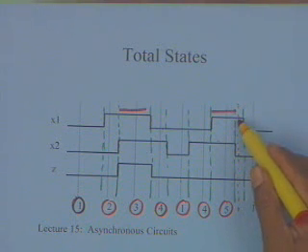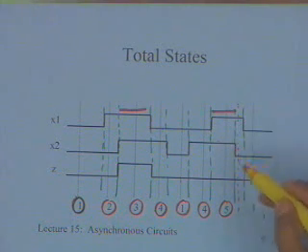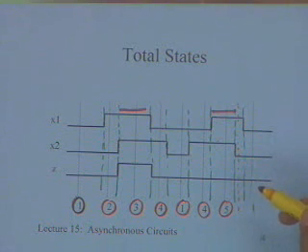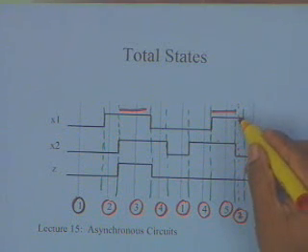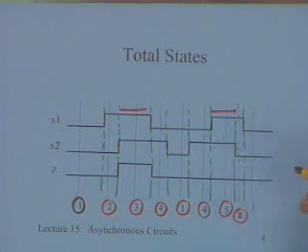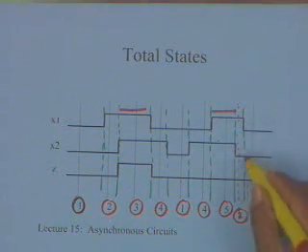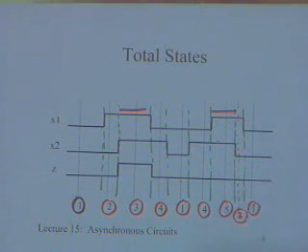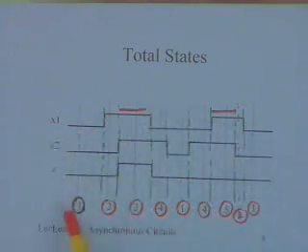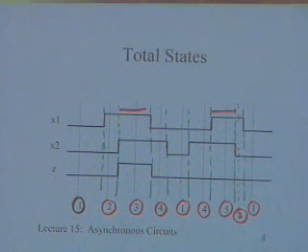So once I go to this 1 and 0, what will be the stable state here? I do not have to distinguish here, because anyway x1 is 1 earlier, then x2 is 0. So when I am 1 0, I can actually go to stable state 2, but actually I go to 0 0 here and I go to 1. So given a problem definition, this particular waveform and marking of these stable states is the starting point.